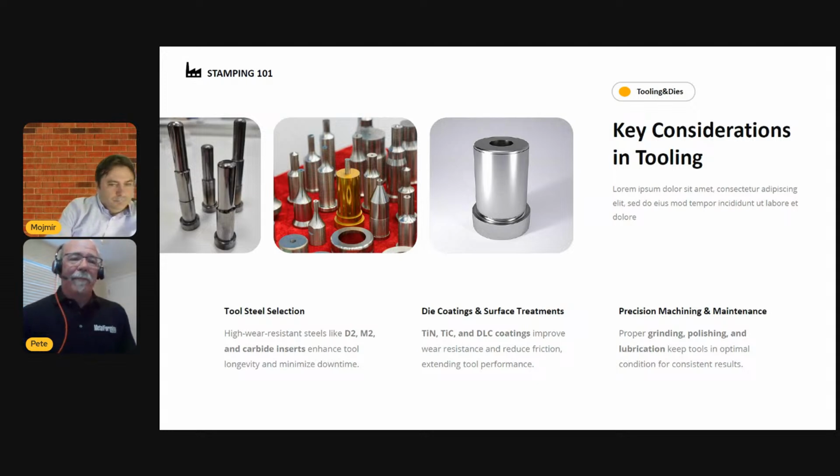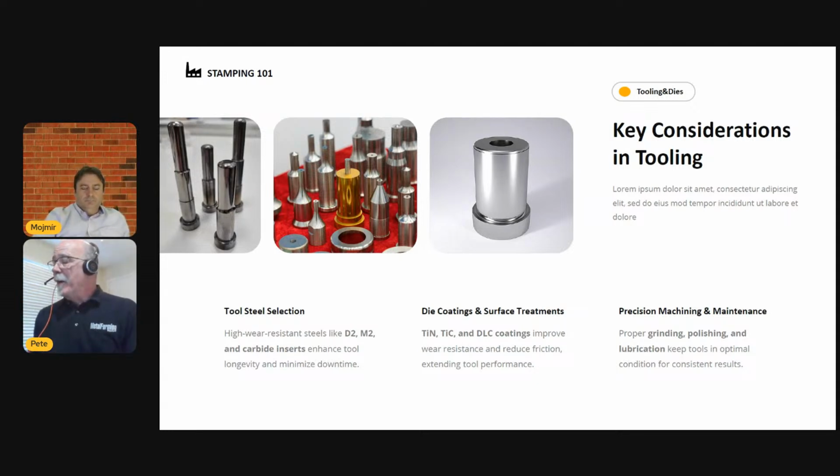That could be a misalignment. That could be poor grinding practices. It could be a poor selection of material. But that I would actually refer to as breakage. Chipping would be much smaller, little chips breaking down on the edges. A tool steel will chip or break because it lacks toughness.